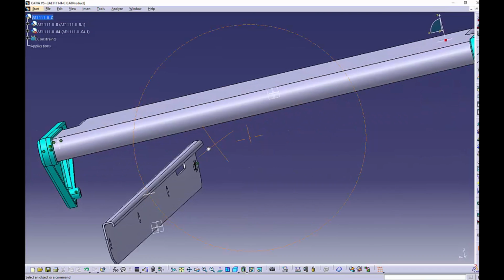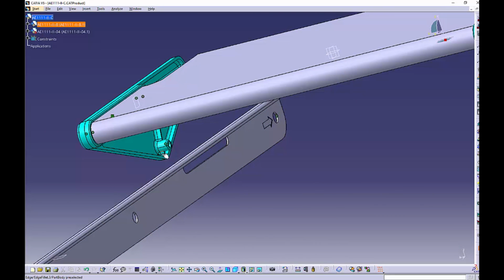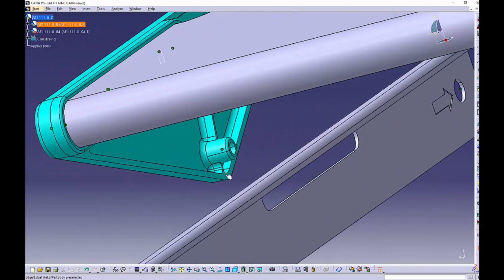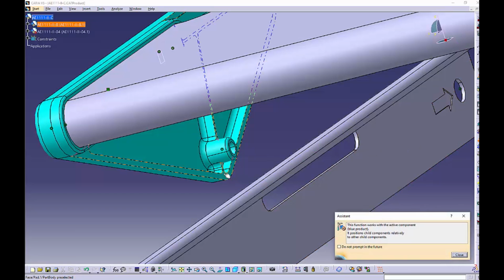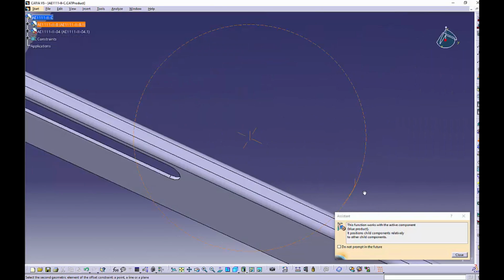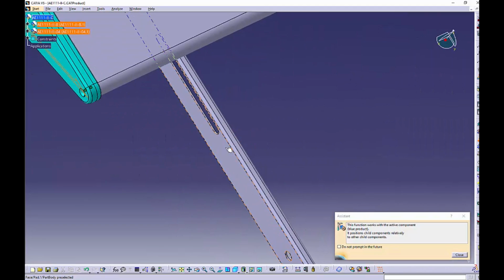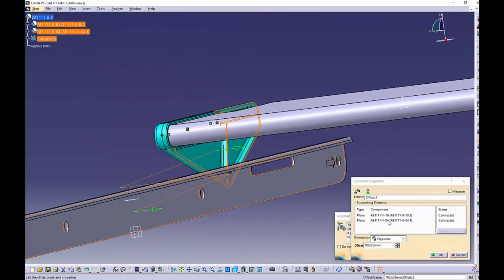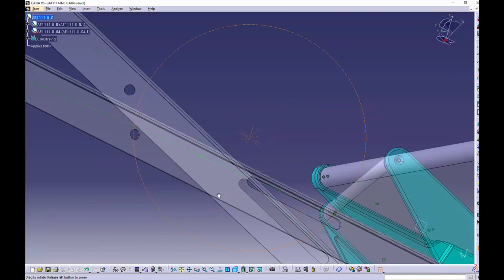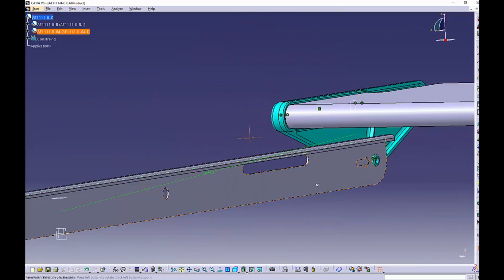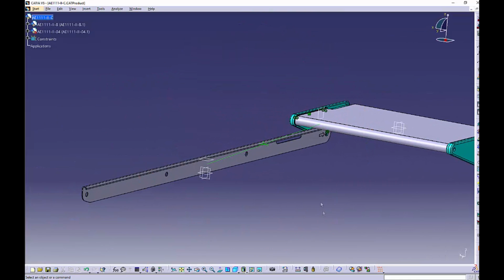And now we also want to have it closer to this, but not touching. If we touch this face, this would stick into our object, and that's not realistic. So we use an offset constraint again, and select this wall, and the outside of our stairs frame, this face. And we make an offset of 2 millimeters. Select 2, and then click OK and update. And this looks beautiful. It fits perfectly. So now we already finished it.